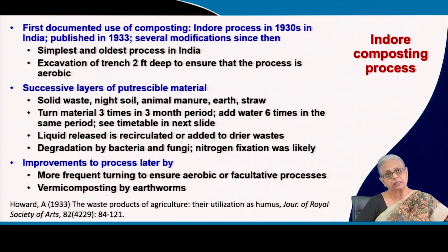So it's the simplest and oldest process in India. All it requires is that you dig a large trench up to 2 feet deep. You don't want to go more than 2 feet deep because it's only up to 2 feet that the process is somewhat aerobic. Beyond that, it becomes anaerobic.